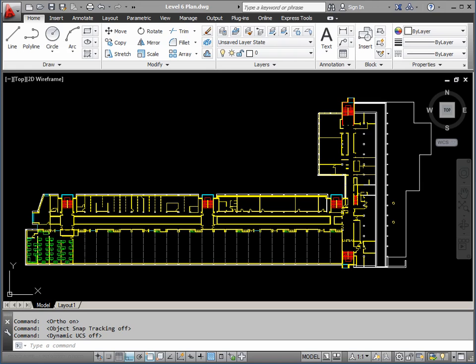Okay, so we've described basically what's happening on the screen. What we'll do is we'll activate a few different object snaps. We'll see what's set at the moment and maybe tweak those. So when this button's activated, it means it will look for these positions on geometry all the time. Okay, they're not active now because we haven't got a command running. There's no command running at the moment, so it's not looking for the geometric points.